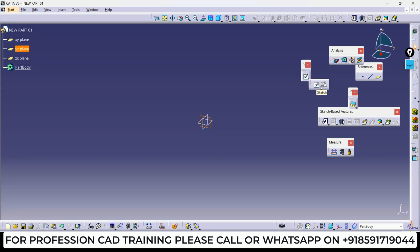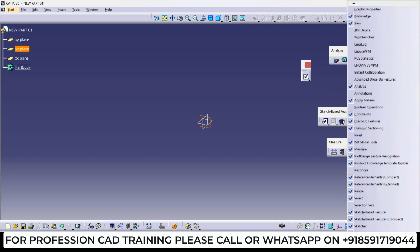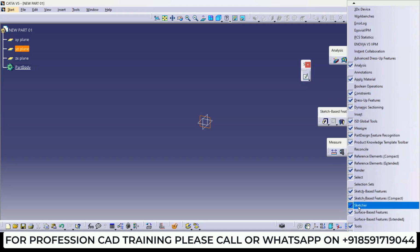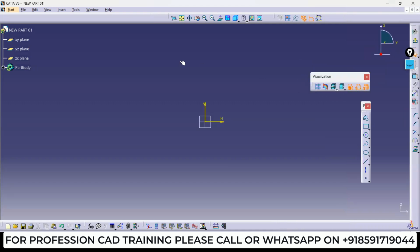Here you are getting two options, sketch and position sketch. If you are unable to find it, just right click on this and go here, sketcher is there, right? You can click on this sketcher and shift to the sketcher workbench. Select the plane and select the sketch, the normal sketch, the first option. Once you click it, you can see this has changed.